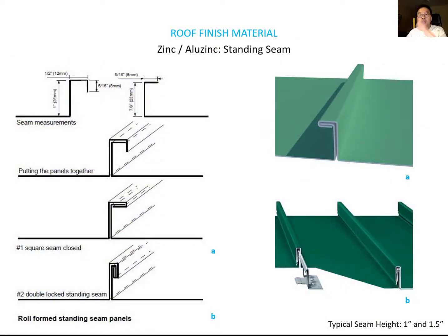Because you have to be connecting the zinc panels together. You can see in this example, you have a first zinc panel, and then this is the next panel. To overlap two zinc panels together, you put the panels together, and it needs to cross one side. You can see they simply overlap the two panels together, and then it crosses this panel here.